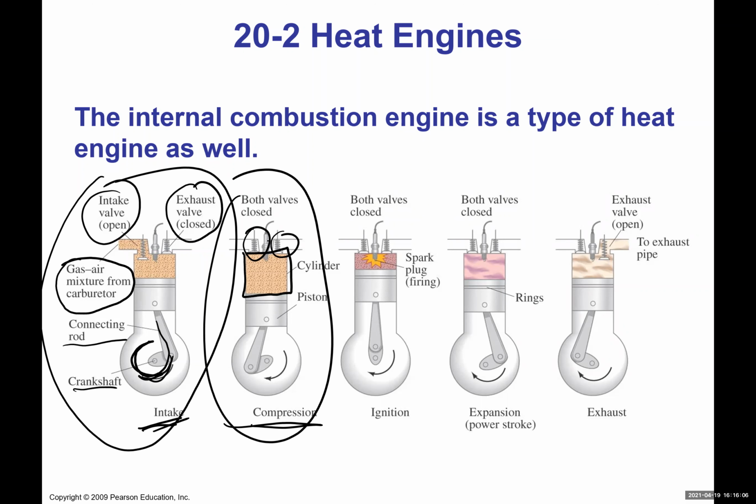compression, the gases have nowhere else to go. So you are compressing them, which means the pressure increases. As the pressure increases, the temperature increases. And you can see, when you really compress them, pressure increases to a really high value, and then the temperature increases so much that you can get some kind of ignition.